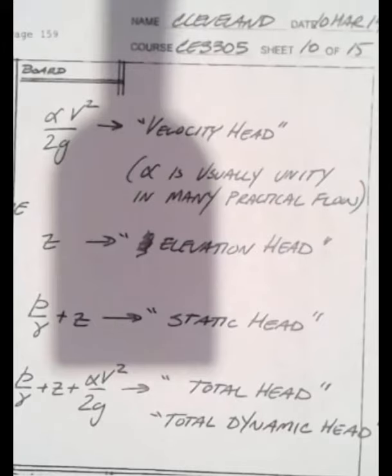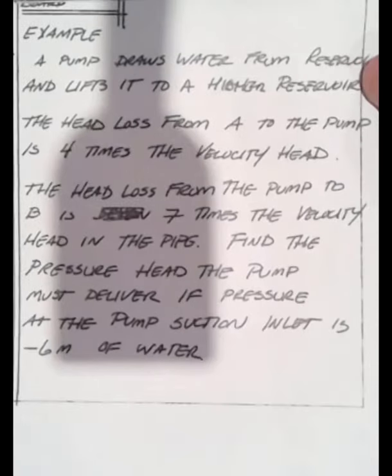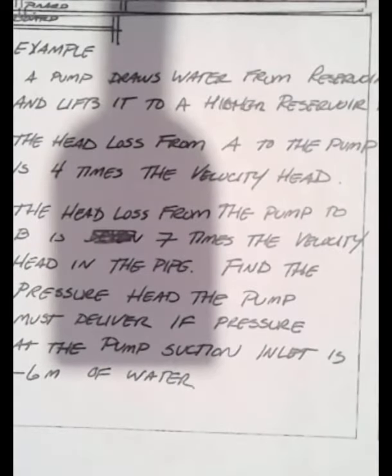The expression as we've developed it is valid for steady, one-dimensional along the axial dimension, incompressible flow in a pipe or actually a flow tube. In the absence of frictional losses and heat transfer, the head loss term would become zero, and we get back to our inviscid flow situation, and it would be Bernoulli's equation as we know it from before. Okay, this particular tool is fundamental in hydraulics.